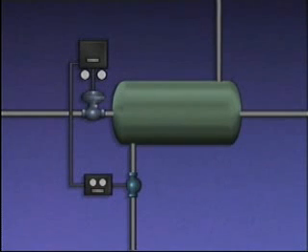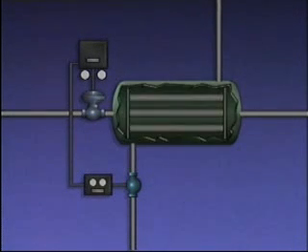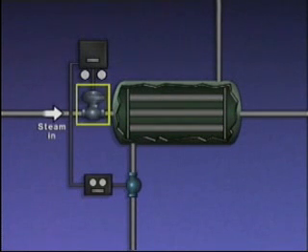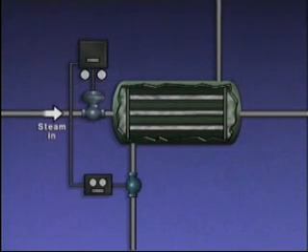One of the basic methods of control used by automatic process control systems is feedback control. In a feedback control system, a control action is initiated after the controlled variable has deviated from set point. To see how an automatic feedback control system works, we'll use this illustration of a heat exchange process. In this system, steam is used to heat water. The steam enters the system through a valve, then flows through tubes inside the heater, and exits the heater through a pipe on the other side.